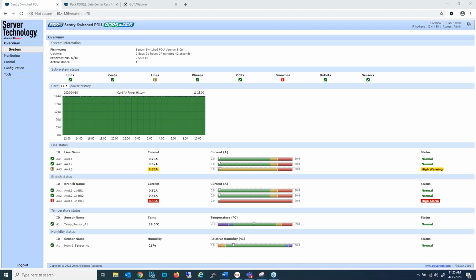That means that 3-phase PDU contains 3 hot lines at the input, a neutral, and a ground. In that case, all of the outlets are wired line to neutral. And the N is your neutral. With those products, the 3-phase Y products, we do actually measure current on the neutral conductor.